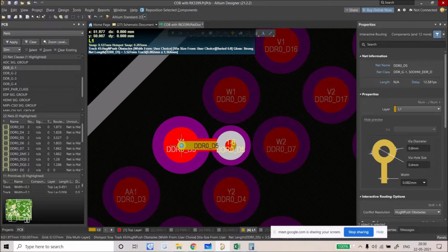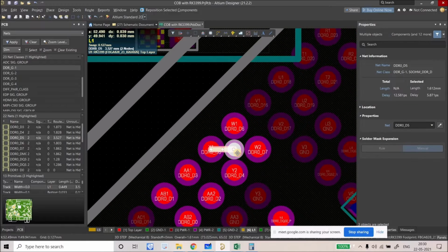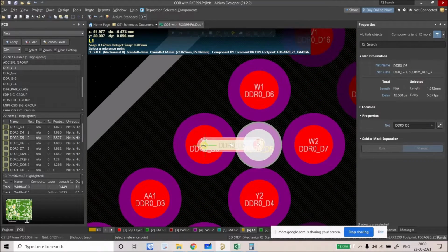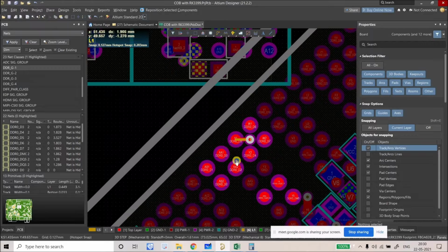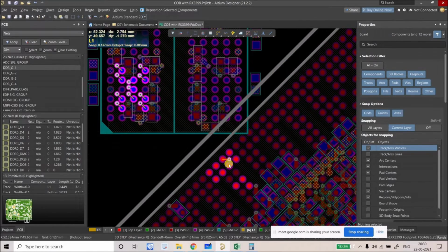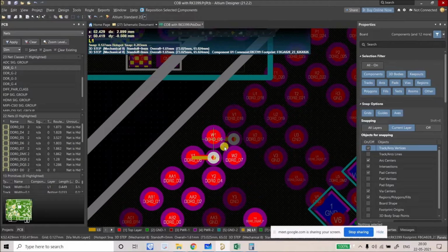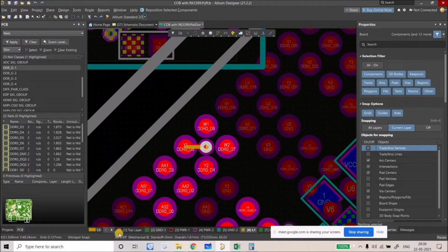Just hold the control key, put that on the center, just select those, and this will be the other template for all the signals, or all the paths, on the top layer, right? And the orientation is kind of correct, right? Because it is following the flow of the connections, right? So we'll just use the same thing, and we'll optimize that during the layout if required.